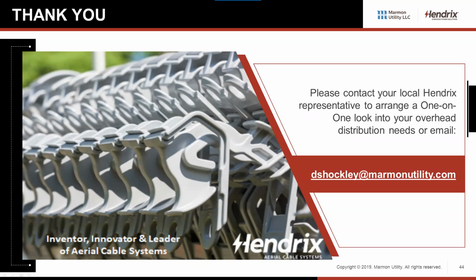We do have clients that will use the longer tangent brackets, even at 15 kV, if they want a little more clearance between the pole and where the phase conductors are. I had a client a couple years ago that told me on multiple circuits where they've got two circuits back to back, they like to use the longer tangent brackets because that gives their linemen enough clearance to work on one phase or one circuit, so they don't have to cover up the other circuit.